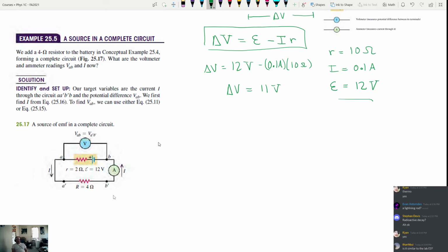So how do we do that? Well, first of all, we can measure the potential difference in 2 different ways. Notice that there's a current flowing through this circuit here. The current is flowing in this direction. You can see it flows out this way, back through here, right? And the same current is going to be flowing through this whole circuit here. We're going to assume that the voltmeter has a very large amount of resistance, which means it's not going to affect the resistance of the system.